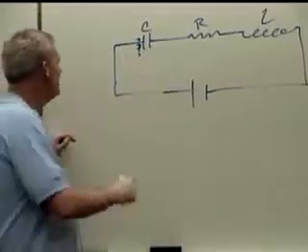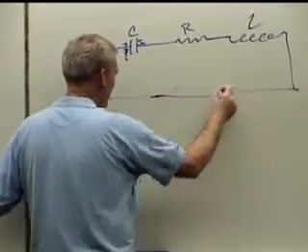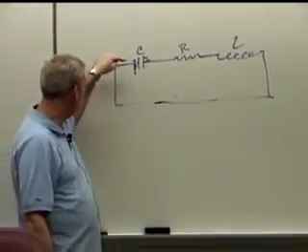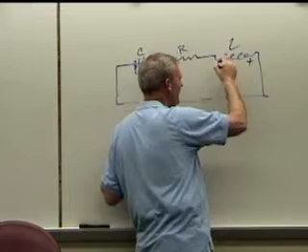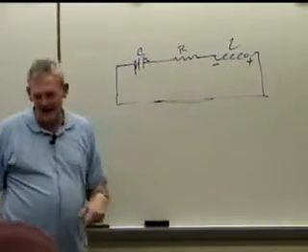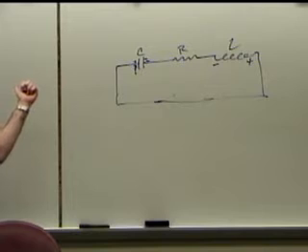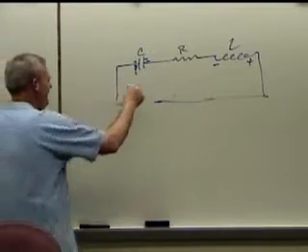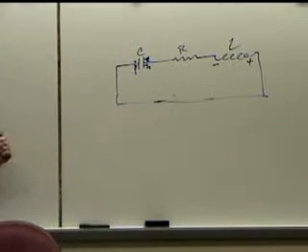It would stop. Then if I took my battery out, this would flow through here, but it would build up in the inductor, and then it would push it back the other way. Then I'd get a bunch of charge building up here, and after it got built up so much, it'd push it back the other way.